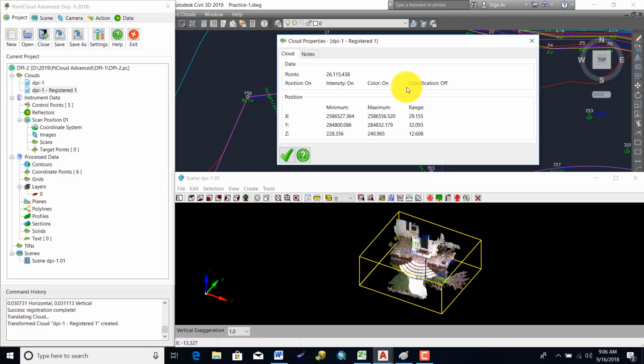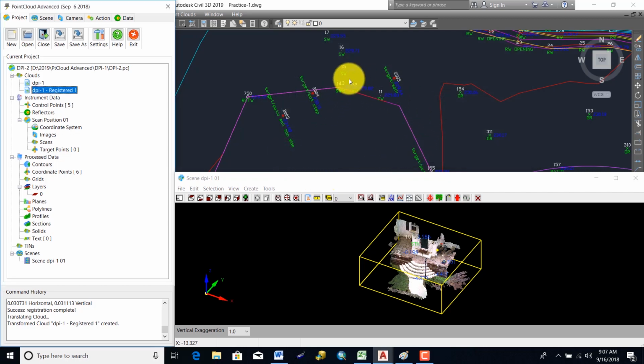That is the point cloud, not broken up into grass, sidewalk, steps, wall, and those types of regions or classifications. Anyway, now position. Notice that the boundings, minimum, maximum, and the range envelop an area that's in this drawing here. I'm going to hit the green button, and that's this drawing right here. So essentially, it took points that I picked in the scan, 1, 2, 3, 4, and 5, at the center of the targets that correspond to the same point numbering of 2001.